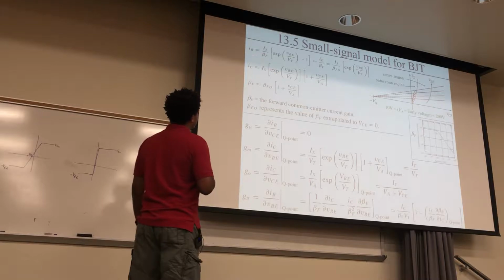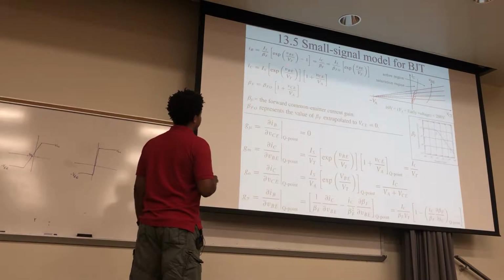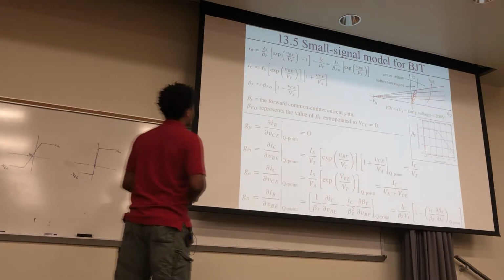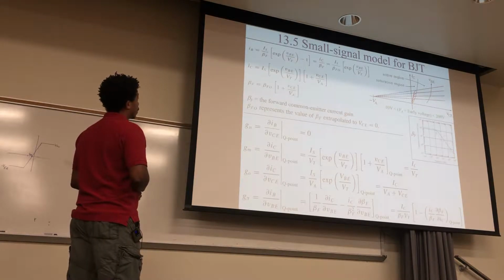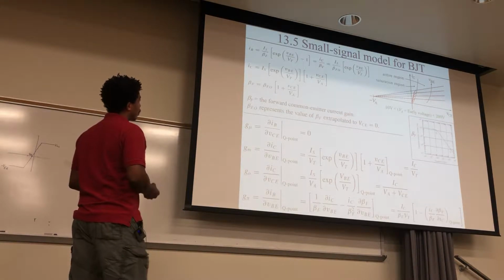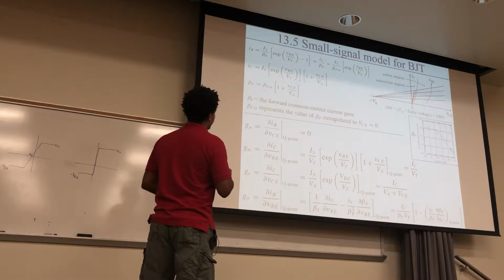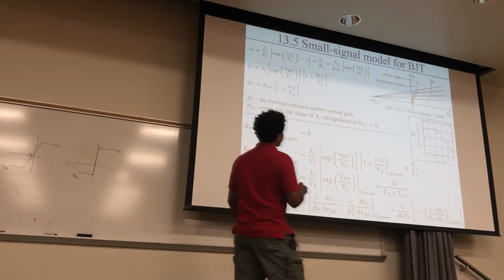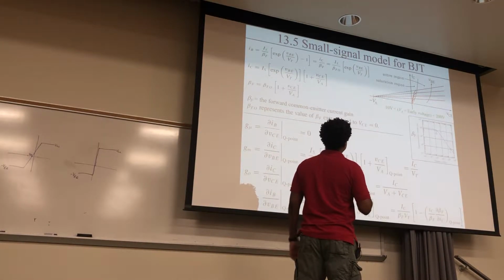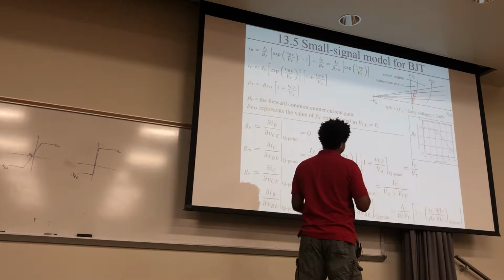What we'll do is we'll take these as definitions, as what these quantities are. Now we've seen this thermal voltage, and we've seen the voltage between the base and emitter. This VA right here, I found a good plot online that explains that. This is called the Early voltage, and that's the last name of the person who made it, which is why it's capital.